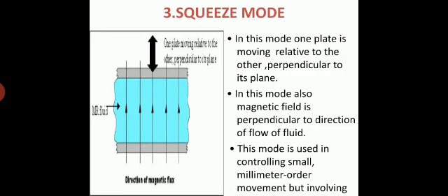Squeeze mode. In this mode, one plate is moving relative to the other, but perpendicular to its plane. And even in this mode, the magnetic field is perpendicular to the fluid flow. And this mode is used in controlling small millimeter order movement but involving high force.